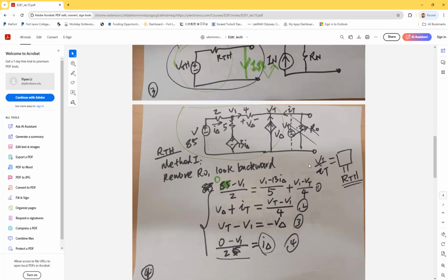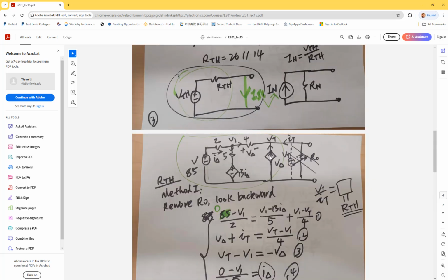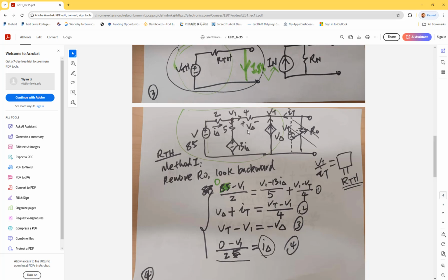So why is it not 50%? Why can you not directly use this equivalent circuit? It's already changing the nature of the circuit. You converted everything into this little equivalent resistor and this source. The original circuit has many other sources, like dependent sources, and some of them are developing power while some are consuming power. However, if you convert it to a resistor, this becomes the overall power being consumed by whatever is in the original circuit. It's changing the nature of the circuit. This resistor is only absorbing or consuming; it's not developing anything. Anyway, come back to the original circuit, find out which ones are developing, and then get the ratio. That's the way to calculate the answer for problem 3, question 3, okay? All right, see you on Friday.